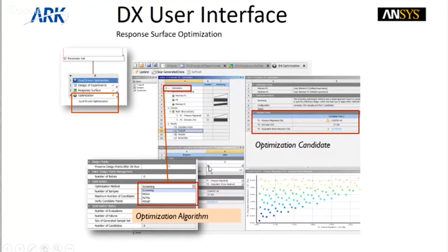Now you can see there is an option over here. I was saying that you can plot the response surface in 2D and 3D plots, and you can select your visibility plot from this drop-down menu. Here, pressure magnitude, extrude depth, and equivalent stress are the three candidate points which we have taken for our parametric study in that example. The results of optimization show that pressure magnitude is the optimum parameter which we need to take into consideration for that particular analysis.